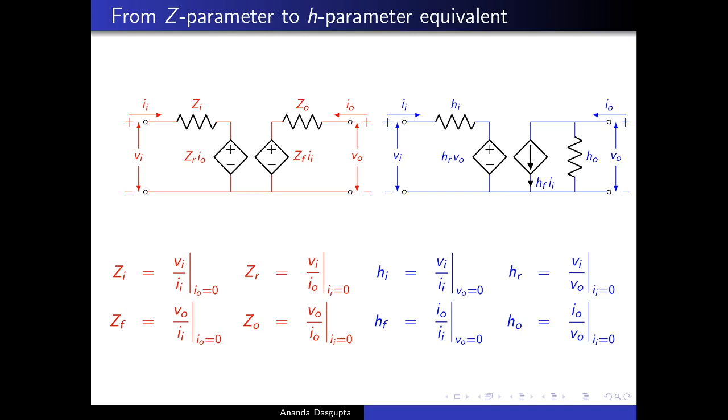And just to remind you, the two-port network theorems are in the context of small signal application. So there is a quiescent point or dormant value for each of these currents and voltages in the circuit. And what we are interested in are fluctuations from those dormant values or quiescent point values. So small ii, small io, small vi, small vo, the ones which are marked in the circuits here, are all fluctuations from the quiescent point values.